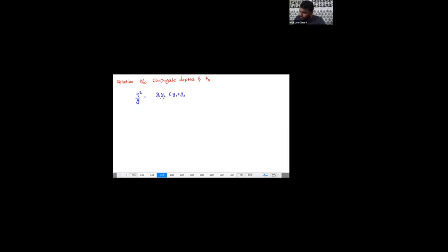Now divide by y1 cube on both sides. Then q square by g y1 cube is equal to, sending the 2 to the other side, 2 y1 y2 into (y1 plus y2) by y1 cube, with the 2 in the denominator.